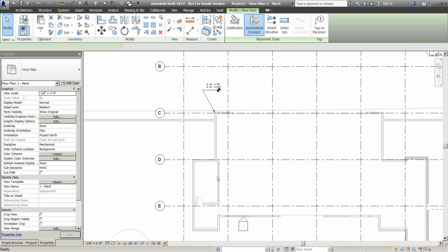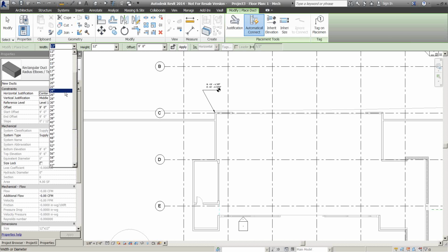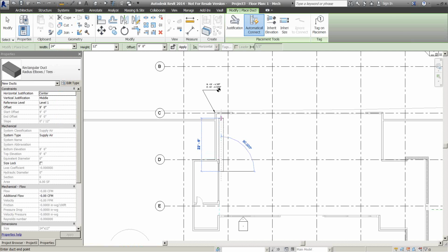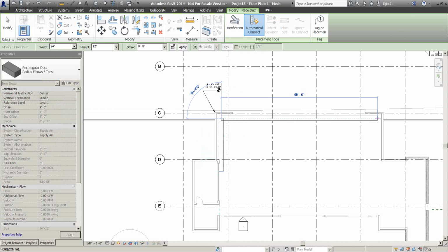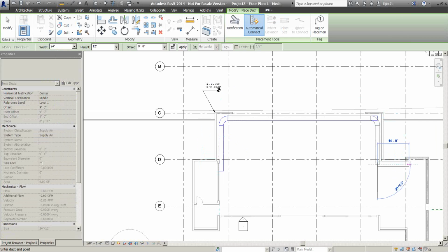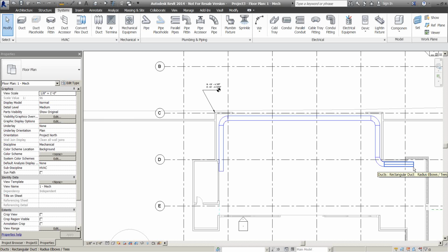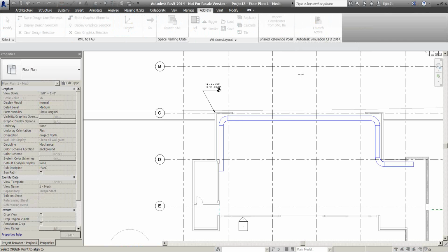I will draw in just a big old dot. It's 24 inch, that's good enough. Just going to run through the inside of this wall just so that we can see if this building moves now, or if our duct moves, or does a marked duct move to follow it. I can throw in some hosted elements if you like, but this one's unhosted, so if the unhosted one moves, then you know the hosted ones are going to move. So I think this follows up a little on what James was asking about.